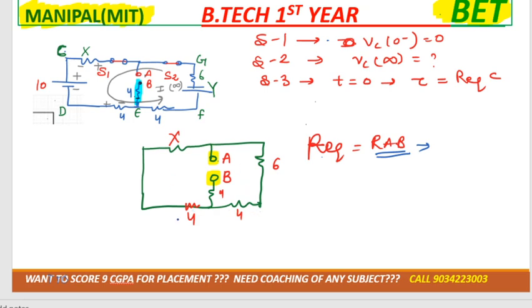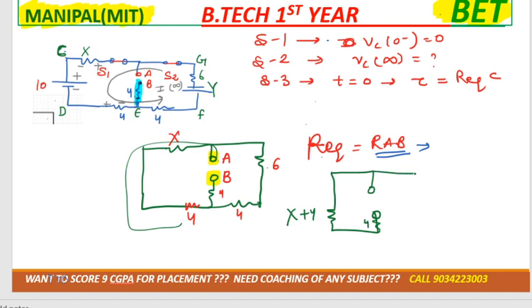If any two resistances are on the same path, that means you can meet both of them, that means they are connected in series. So X and 4, you can meet both of them, so they are connected in series, that is X plus 4. Similarly 6 and 4, you can meet both of them, right? So these are connected in series, that is 10 ohm.